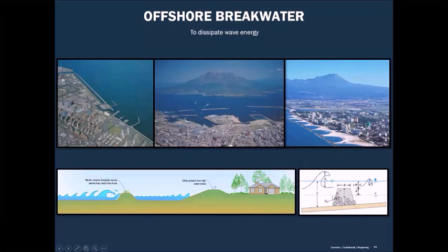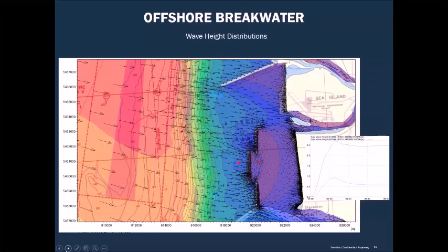propagated. And when you place this type of structure, between this dike and this structure, the sediment movement and the flow pattern will be changed. So that should be taken care of in the model, which area will be the best and what is the size of the breakwater. So that can be done by considering the model.